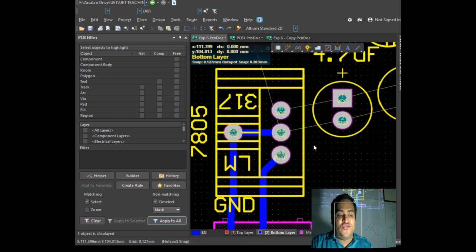now one thing very important: up till now the heatsink was not connected with anything. Now the additional information: whenever there is a regulator on your Vero board or anywhere, this metal part is always connected with the center pin of any regulator, which means it is connected with the ground. So I am using this one; the heatsink will be connected with a screw, so it is going to be a connection, and this is connected with the center pin over there.